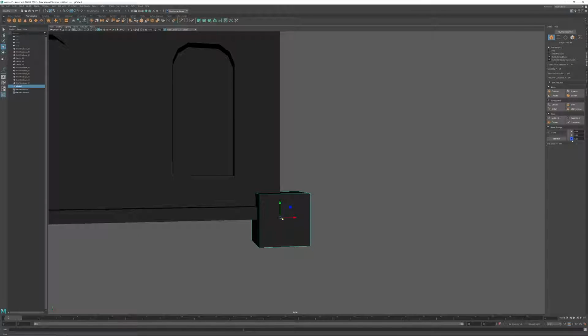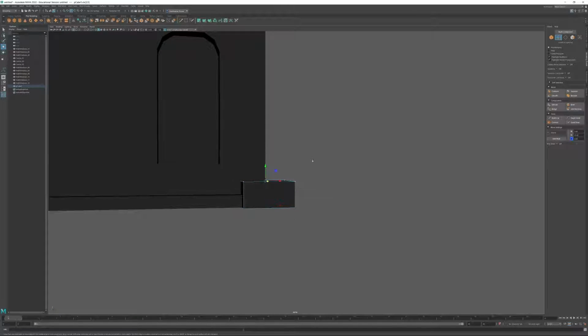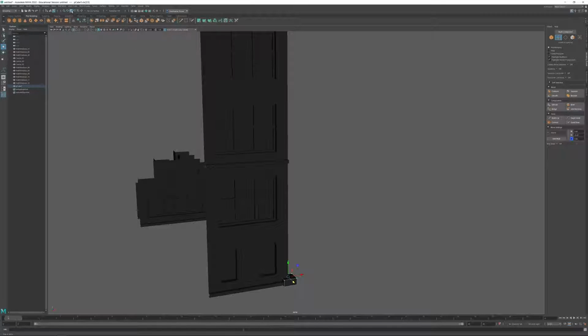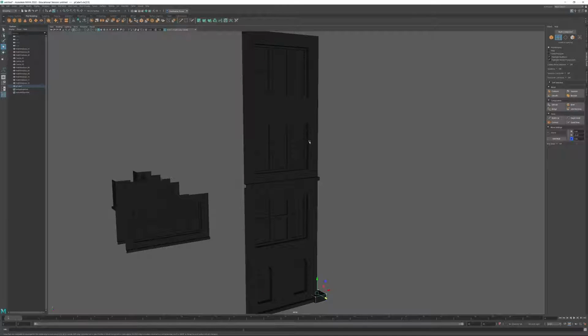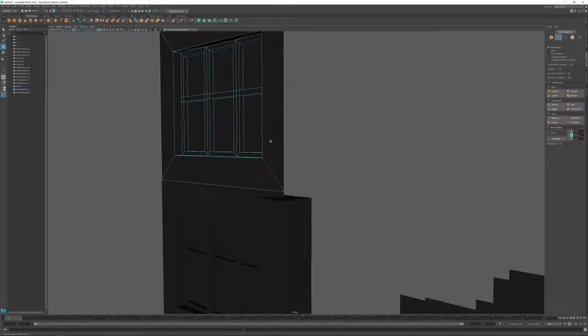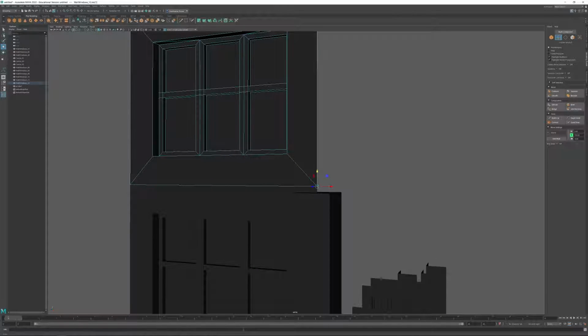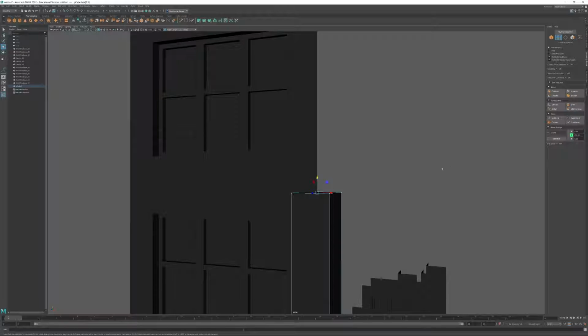Let's take a look here. We're going to go into vertex mode, and I'll put these on the ground. This is going to become 0. I will grab the top ones, and let's turn off our snaps here so they don't interfere. I essentially want to bring this all the way up to that third story. If I look at the height here, that height is 700. That makes it pretty easy to put these in the right place. So we'll put 700 in. That's 7,000. There we go, 700.